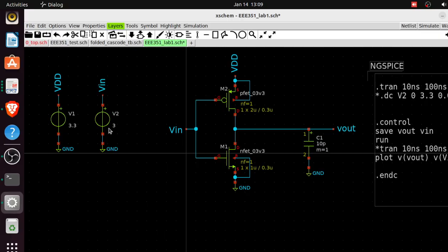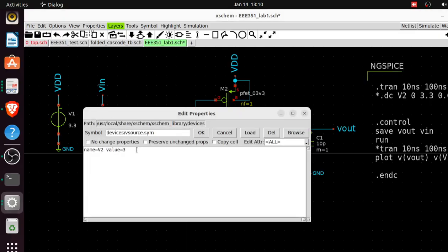input voltage source, which would have to be a time varying kind of source. For digital simulation like this, I want to use a square wave, right? Something that rises, then gets flat, maybe that will be a 0, then it comes down again to be a 1. So to do that, that's my V in, that I'll make a pulse kind of square wave voltage form. So I'll just double click and remove that 3.